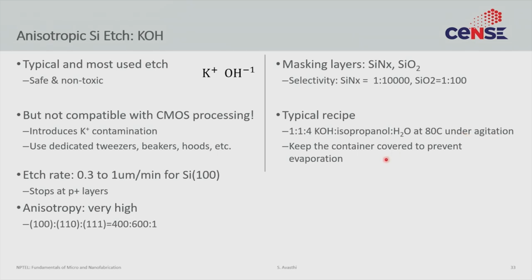Finally, these etches tend to be fairly long. Sometimes you want to etch very deep structures, which takes a long time, hours. So during those hours, you don't want the concentration of your etchant to change too much. So often this etching is done in a closed container where the etchant just does not evaporate away. So at 80 degrees C, if you are keeping things for a few hours, you can imagine most of the water will just evaporate. So you have to prevent that from happening.